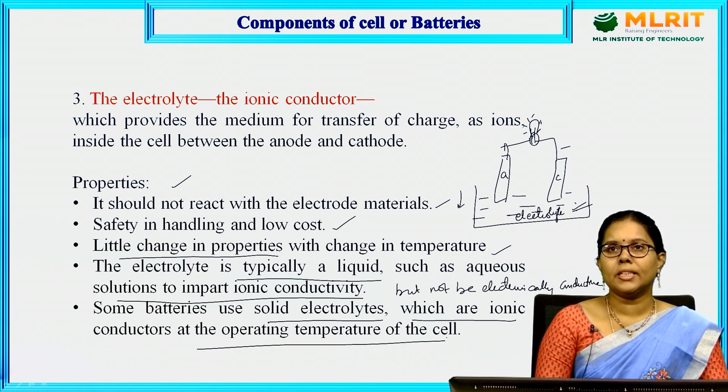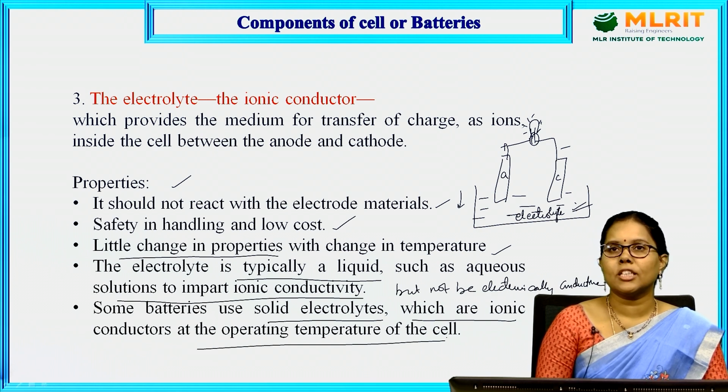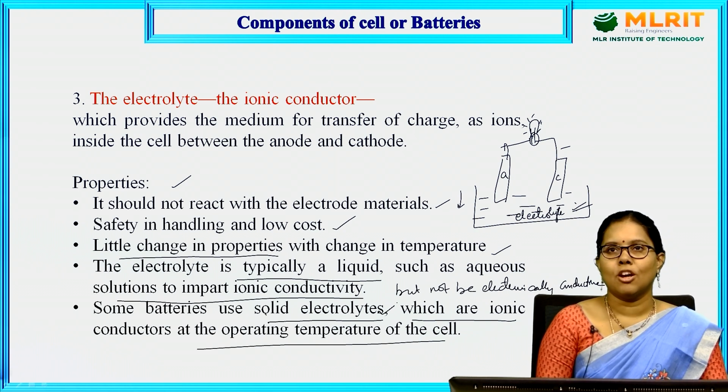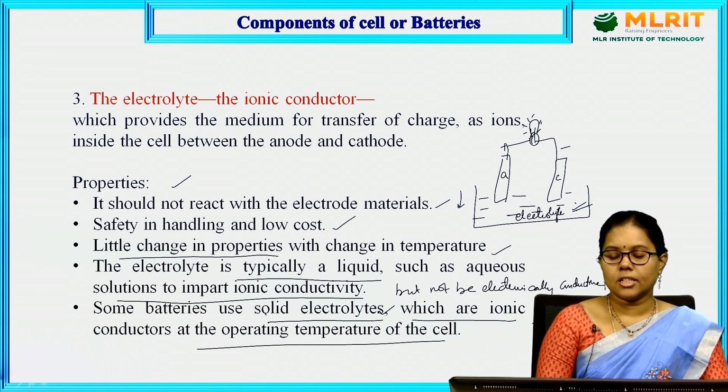Lithium batteries cannot be used with an aqueous electrolyte solution if lithium is the anodic metal. In thermal conditions, we cannot use aqueous electrolytes. In such cases, we go for solid electrolytes, non-aqueous electrolytes, or molten salts, which are ionic conductors at the operating temperature of the cell.